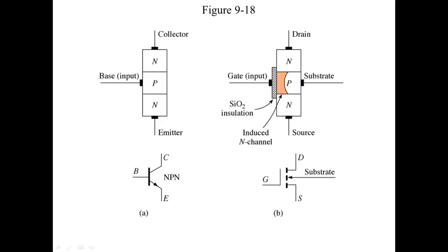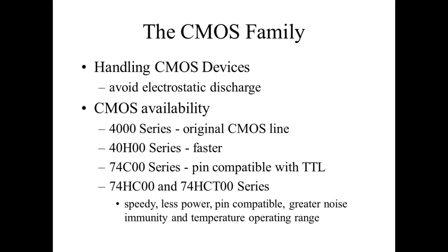So the advantage of TTL over CMOS is that it's faster, but the biggest disadvantage is it consumes a lot more power. And if I'm not concerned with speed, then odds are we're going to use MOS. Now, they came out with a 4000 series, and it was totally not compatible with TTL. They did that on purpose so people wouldn't screw up and put these things together, because a CMOS gate would not run a TTL gate at all. It just couldn't put out the current required to do that. But then they started coming out with newer families, so the 4000 series are getting harder to find because of these.